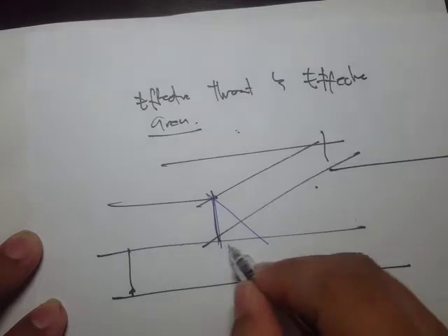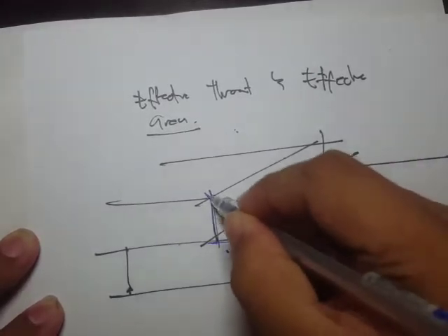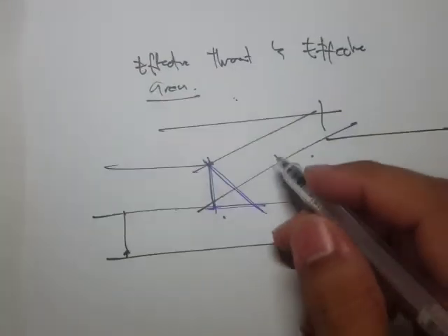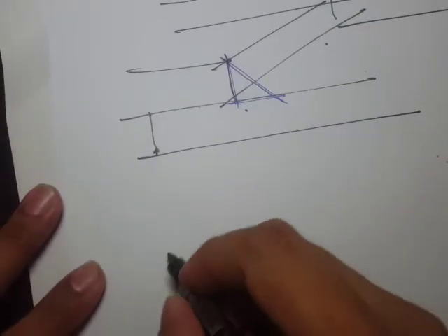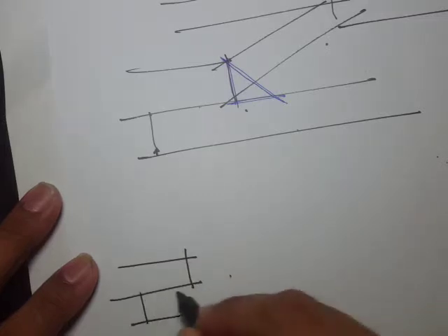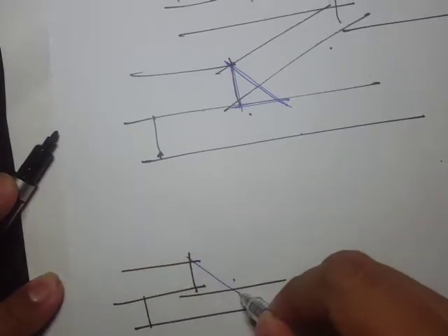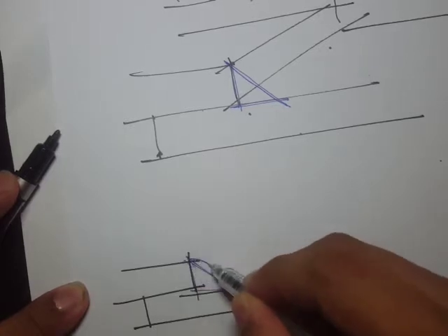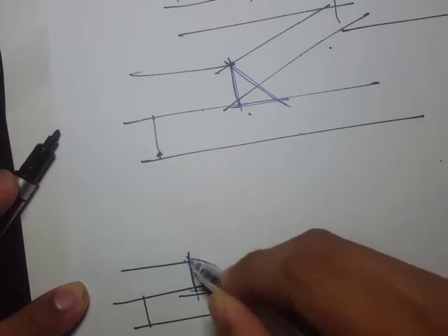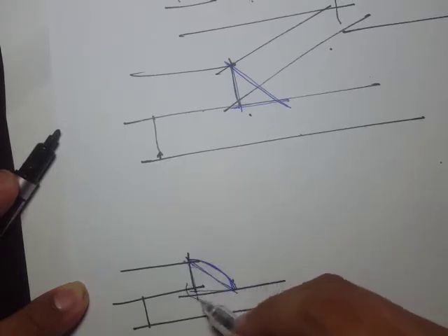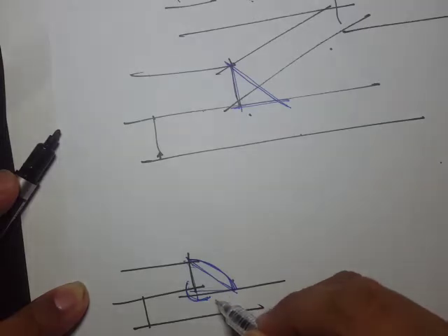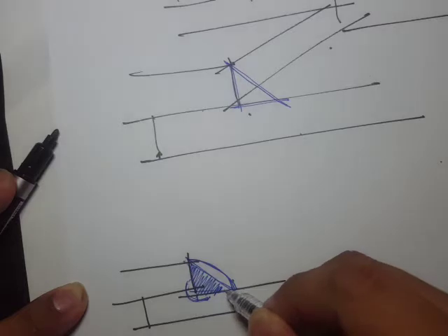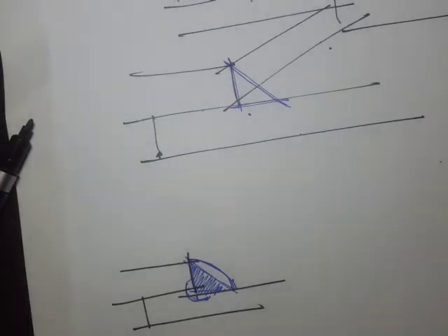Okay, so this is my weld. Of course, this is an idealized shape for the fillet weld joint, because the actual one could have some weld materials over here, and it can also have materials over here for the penetration, but we will only consider a triangular shape.